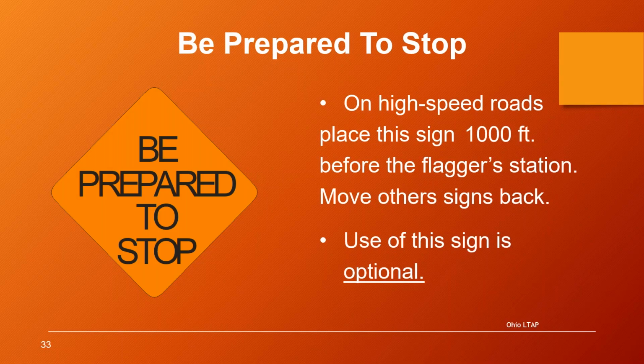And then, like I said, the "be prepared to stop" sign is optional. We place this sign 1,000 feet before the flagger station. So if you use it, that would be the third out of 4 signs.